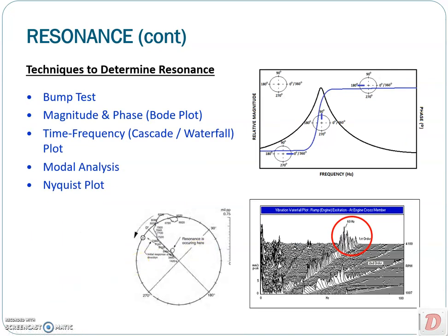Some techniques could be used to determine the resonance or natural frequencies. They are bump tests, where a force is applied on the structure and the response due to this force will give the natural peak or frequency.